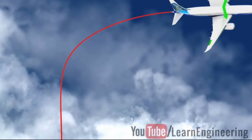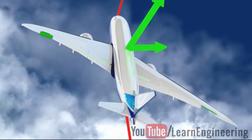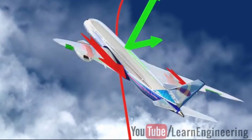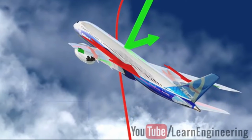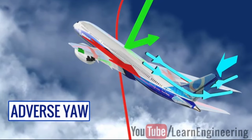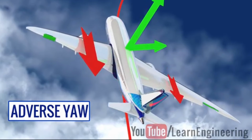However, this banking technique has some drawbacks. When you keep one aileron up and the other aileron down, the drag forces induced on the wings are not the same. This will cause the airplane to yaw. This phenomenon is known as adverse yaw. The rudder has to be operated simultaneously to prevent the adverse yaw.